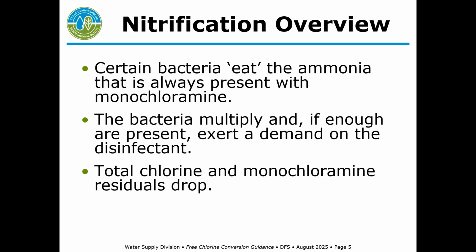During nitrification, you have bacteria in your distribution system. Our distribution systems are not sterile by any means. There are definitely bacteria, and for the most part, they're not harmful to us. And the particular nitrifying bacteria we're talking about are not harmful for us to drink. However, if they multiply and get out of control, it can exert a demand on your disinfectant. And then, of course, total chlorine and monochloramine residuals drop.